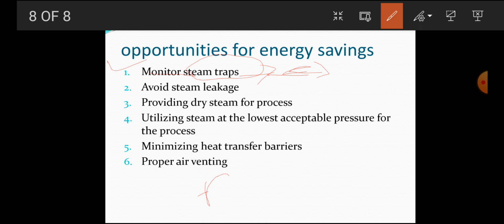If steam blows out continuously in a blue stream, it is leaking steam. If steam blows out intermittently in a whitish cloud, it is flash steam. So the difference is that flash steam is not continuous, it is intermittent, while leaking steam is continuous because there is a leak.